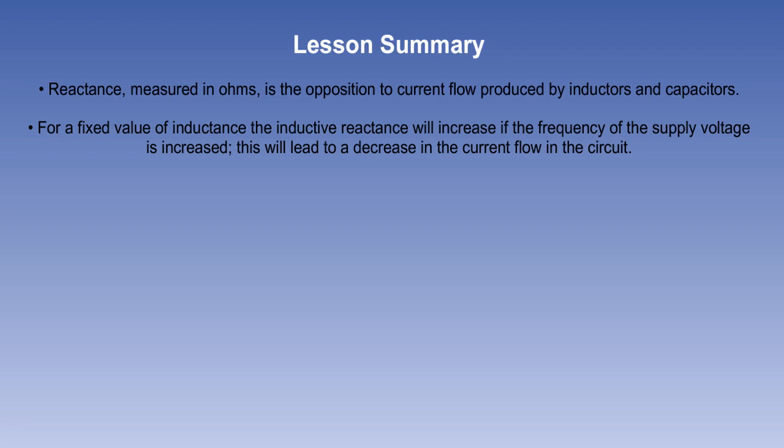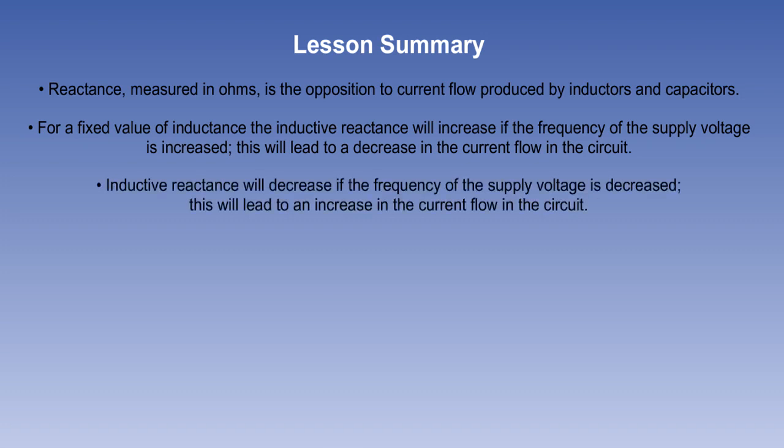For a fixed value of inductance, the inductive reactance will increase if the frequency of the supply voltage is increased. This will lead to a decrease in the current flow in the circuit. Inductive reactance will decrease if the frequency of the supply voltage is decreased. This will lead to an increase in the current flow in the circuit.